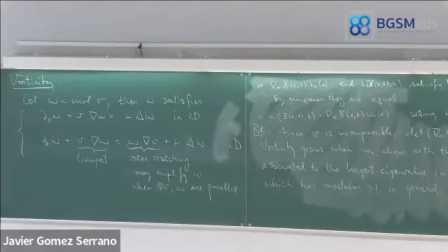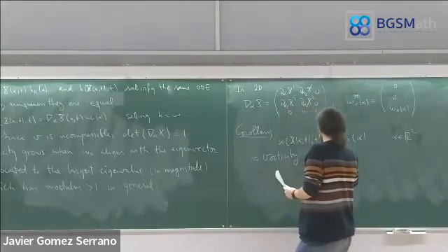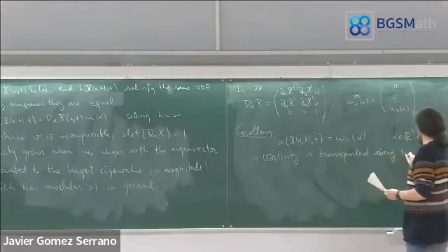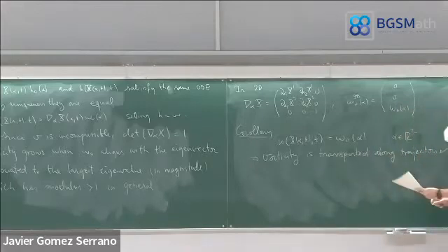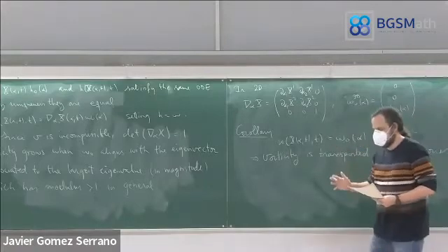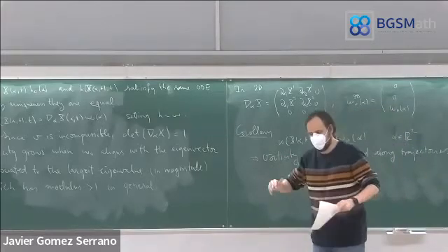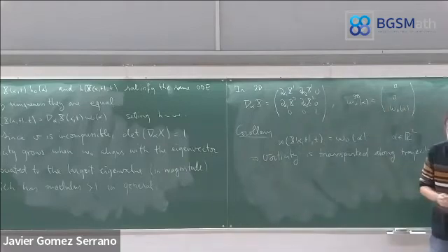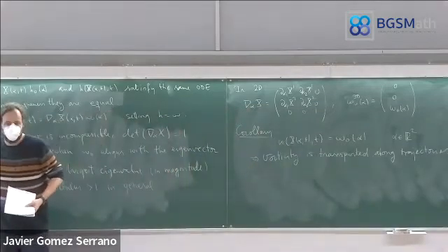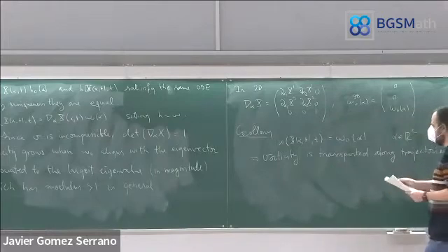We can see from these two points of view, Lagrangian and Eulerian, that exactly this happens. If we were to start with a block of vorticity, then the block will move here and there, but it's not going to dramatically increase. This also goes along the lines that for 2D there is no blow up, because the vorticity is going to depend on the initial data.